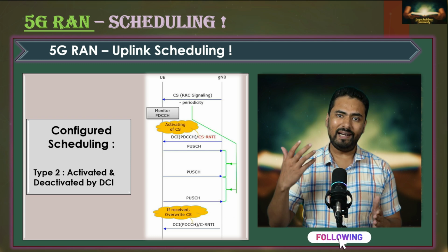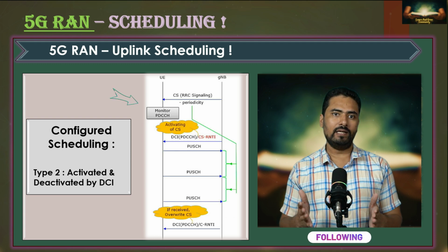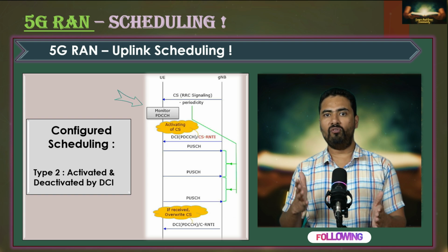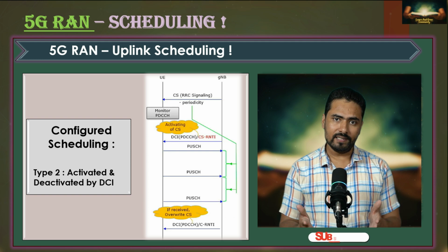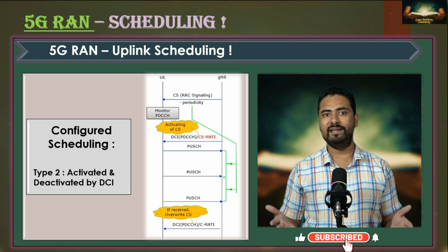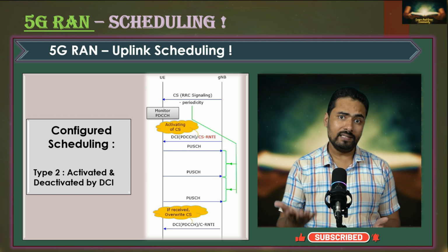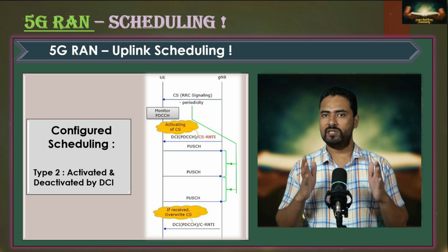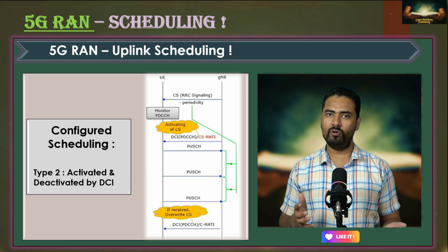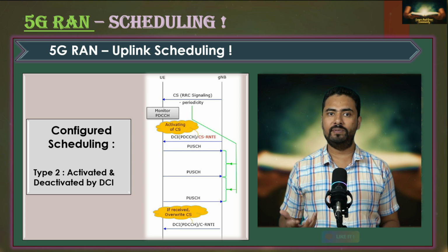So depending on the packet arrival time, the PDCCH can be used to adjust the fraction of grants that are actively used. Although this approach increases the signaling overhead on the PDCCH, it enhances the efficiency and minimizes resource wastage. It was just a brief, as this series is focused on introducing different concepts of 5G NR.